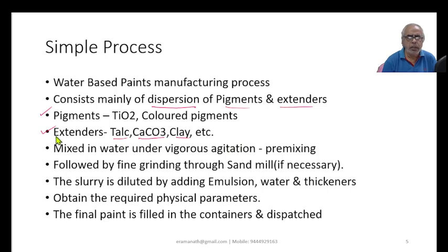And as I already mentioned, these extenders are surface fillers, so that they can fill up the surface. That is, if the surface is rough, it will smoothen. And in fact, that is the main objective of application of paint, to hide the surface, is it not? Therefore, opacity is a very important term to be considered.